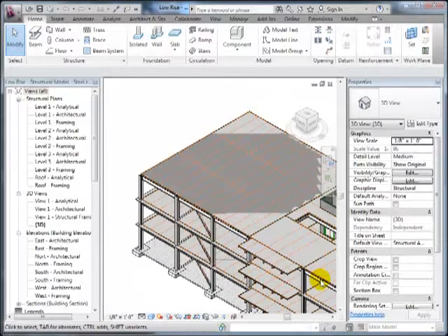Okay, the idea with the building modeling tools is that we can start to create pretty realistic 3D models of what we're trying to construct and then use those as the basis for visualizing, for creating the construction docs, or even doing analysis and simulation on them. Because these models are not just graphical representations for producing the views, they actually understand real things. They understand weights and loads and stresses and properties so that we can do things like structural analysis or start to think about things like, for this space, how much air needs to flow into this space, and track that back to how big the air handler has to be to supply the HVAC system.